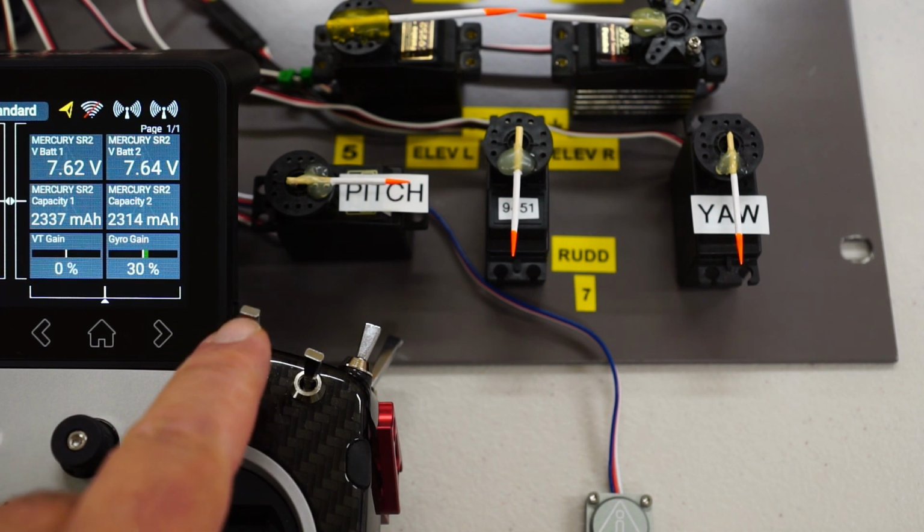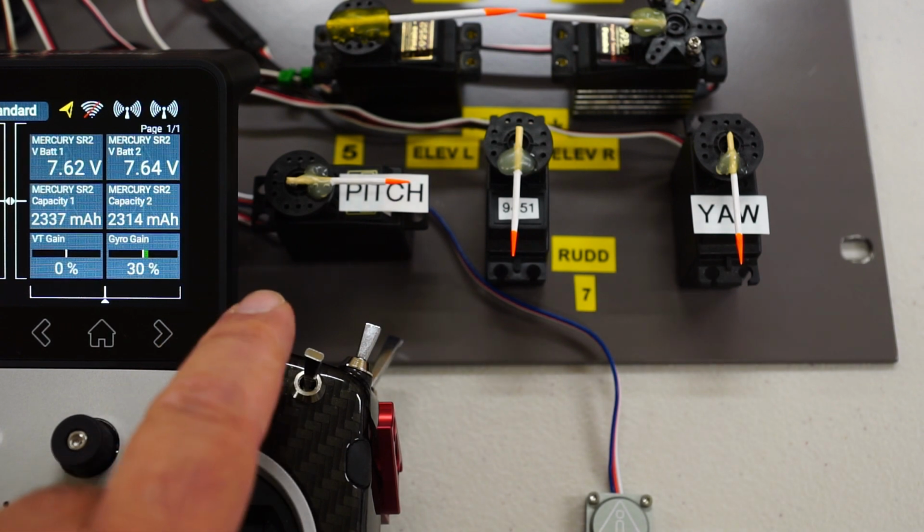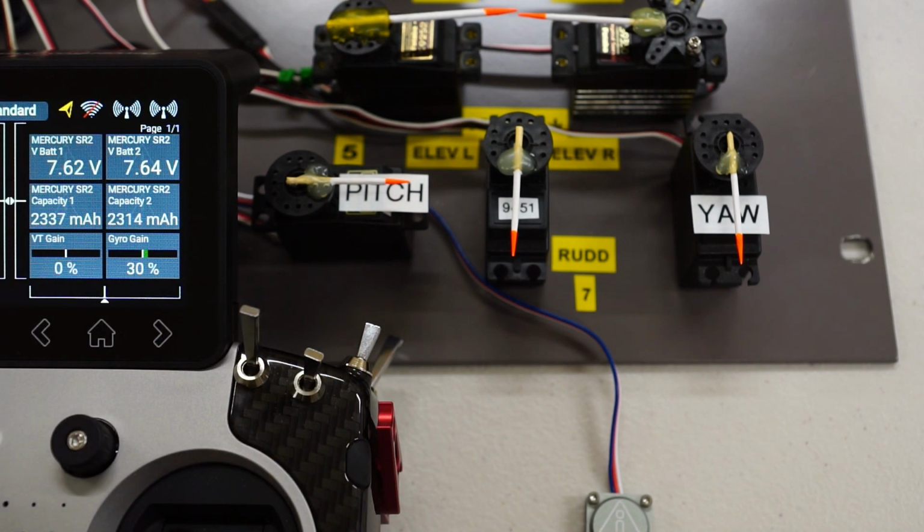And like I said, if you don't want to flick a switch, in this situation you want to tie it to your flight modes. You just select, instead of global, you select single, and you set those rate settings per flight mode. Basically, you can reduce the rate. You can even include a switch with different flight settings. It gets a bit complex, but it's easy enough to do with either flight modes or a single switch, and pretty much that's it. That's how you do it.